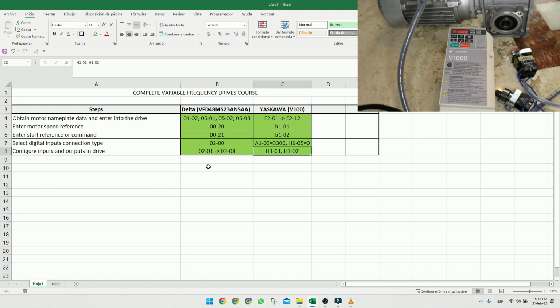You're going to have to change your full motor or your motor reducer, when you could have tested the tuning so that the gains were properly adjusted and you could adjust the type of control needed for your application so that they could be matched, and that way you wouldn't have to buy a bigger motor.